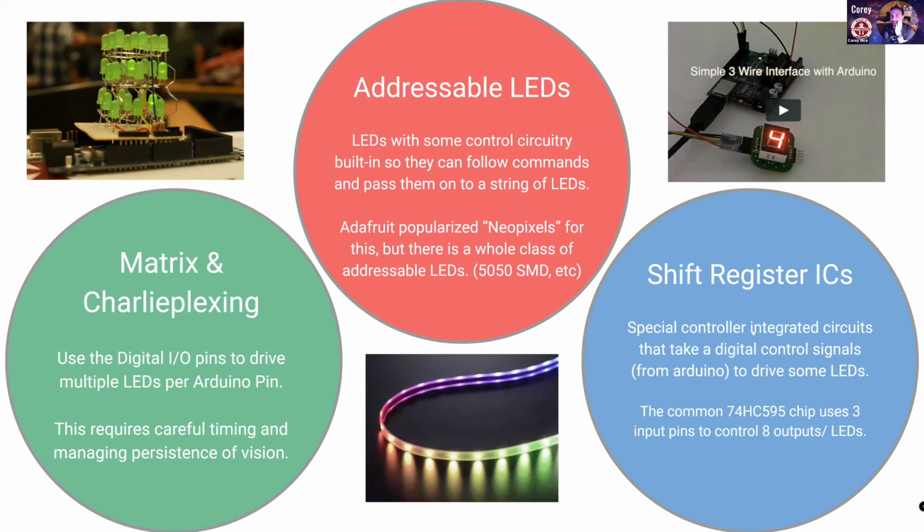And then the last one is shift registers. And these are sort of an older solution for this, but they're really great. You can use them as other integrated circuits you add in, and they let you multiply your connections coming out of the Arduino. It takes 3 pins from the Arduino, and you can use a shift register integrated circuit, which is just another chip that looks like the ATmega, and that will output to 8 more things.